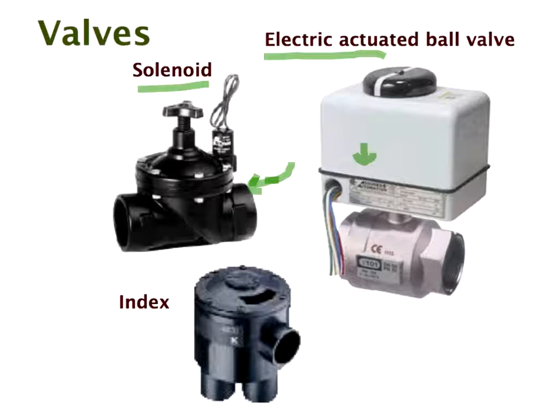They cost more, but again, it's cheaper than having a freezing situation, and some engineers prefer it to putting a bleed around the valve so that it is bleeding back all the time, irrespective of whether the valve's open or closed. Then, of course, index valves are used between zones to go from zone to zone instead of using solenoid valves, and they just cycle.